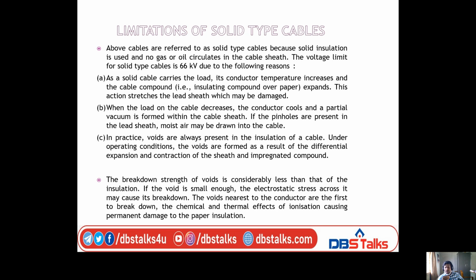The voids nearest to the conductor are the first to break down, then the chemical and thermal effects cause permanent damage to the paper insulation. These are the limitations of the solid type. That means load increases, temperature increases, such that the cable diameter increases, and it may be stretched in the lead sheath, so sometimes it may be damaged. Suppose load decreases, temperature decreases, that may form some pinholes in the lead sheath. So therefore moisture may enter into the lead sheath, right?